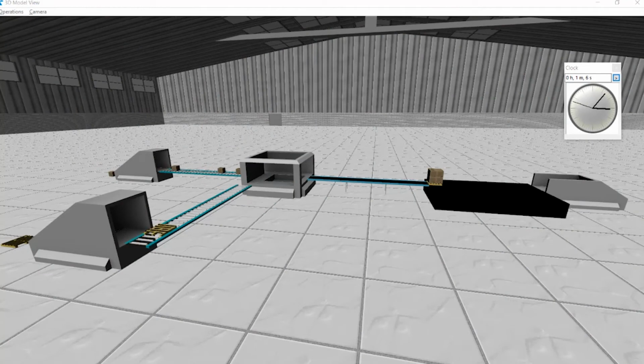Enterprise Dynamics library contains a complete set of simulation objects which allow you to create different types of models. In this Get Started tutorial, we will explain several of these objects, such as the container, assembler, unpack, and conveyor atoms. The container atom is used for storing or stacking other atoms, typically product atoms.